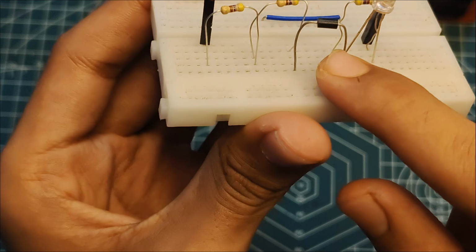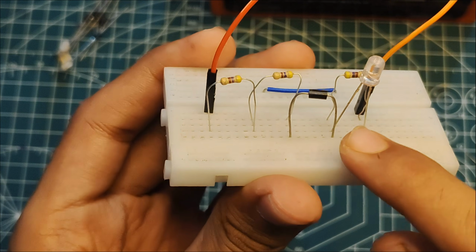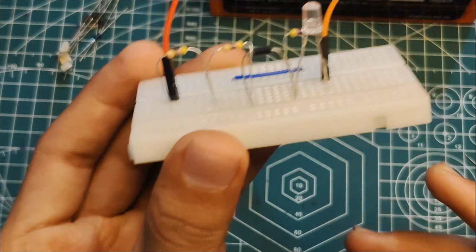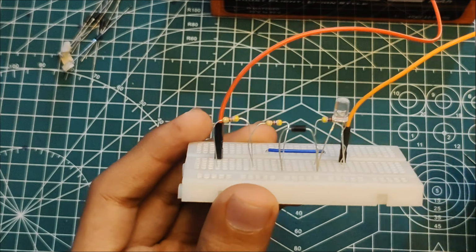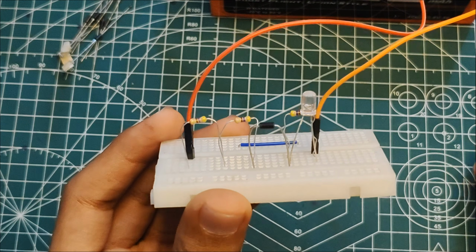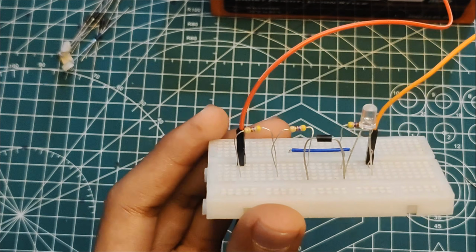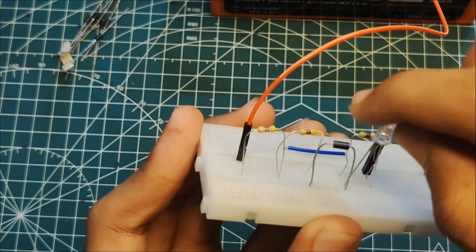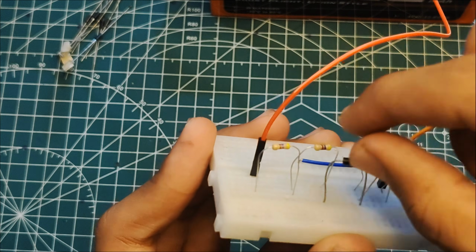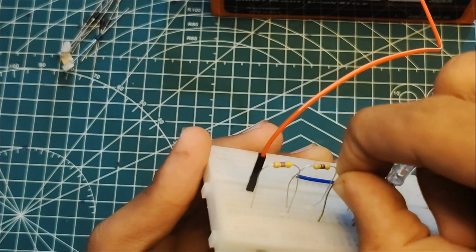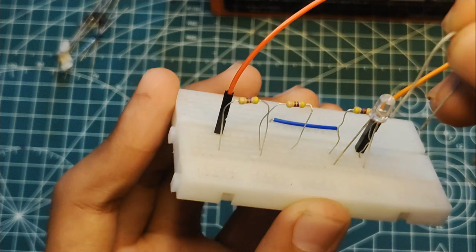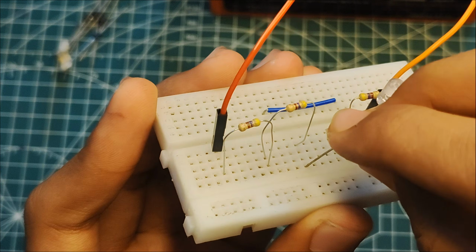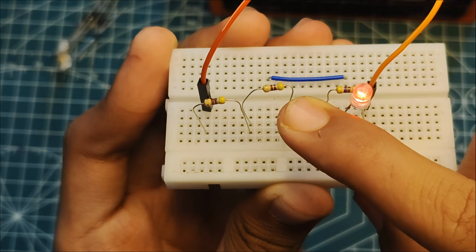So you can see that when we flip the diode to the opposite side, there is no current in this direction. This means that the diode only allows current in the forward direction, which we call forward bias, and there is no current in reverse bias. If we flip the diode in the opposite direction, there will be no current except a very small, minute leakage current. And when we flip it again and put the silver on the forward side, this will make it forward bias, and the current will start flowing again, and the LED will glow.